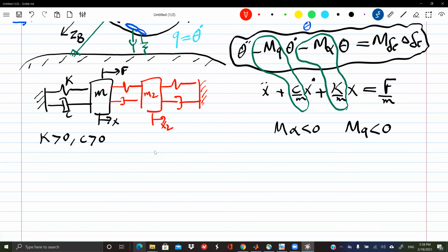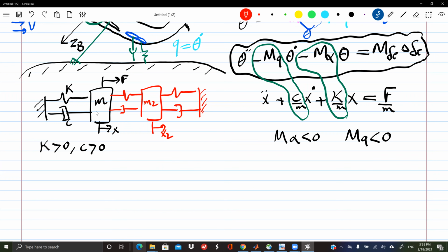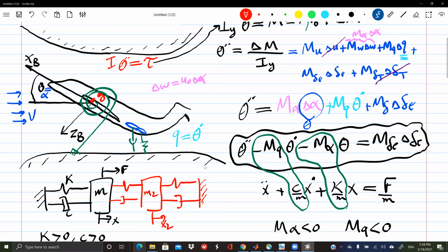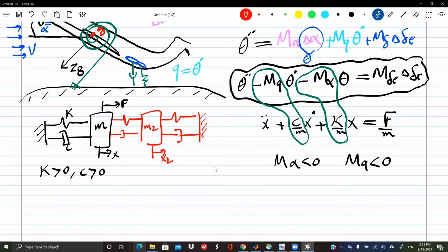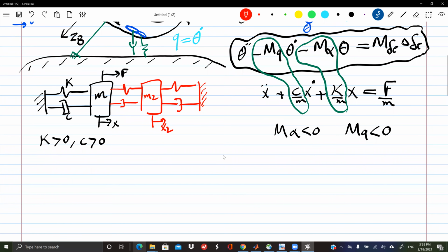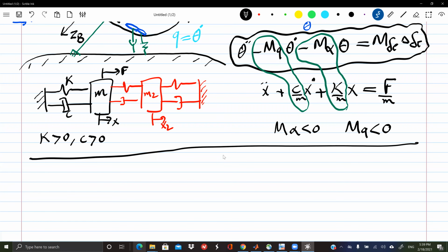Okay, so now it's not just I need to have a stiffness and damping. We need a rigorous theory, because we have a 6 degree of freedom system, so it's multi-degree of freedom. It's in free flight. They are interacting with each other. Roll affects yaw, affects roll, affects pitch, non-linearly, and so on. So we need a rigorous stability theory. Any question about that? Okay, so we need a theory.